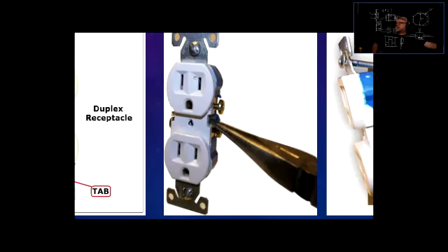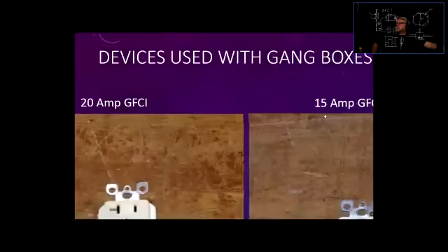So when you plug in a coffee maker here, and then you turn on the microwave oven, then it's not going to draw too much current. Or a tea kettle and a microwave, they are going to overdraw, try to get too much current, and the circuit breaker is going to flip. So this way you can have two separate devices plugged into two separate circuit breakers.